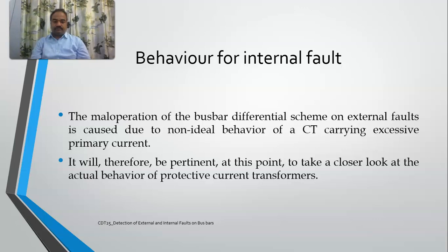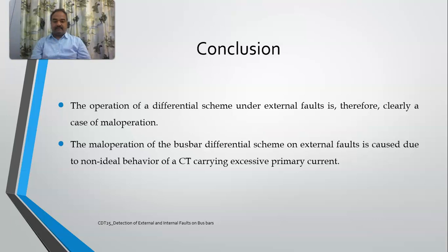So the maloperation of the busbar differential scheme on external faults is caused due to the non-ideal behavior of a CT carrying excessive primary currents. Understand? This non-ideal behavior of CT causes maloperation in case of external faults. This is the conclusion.